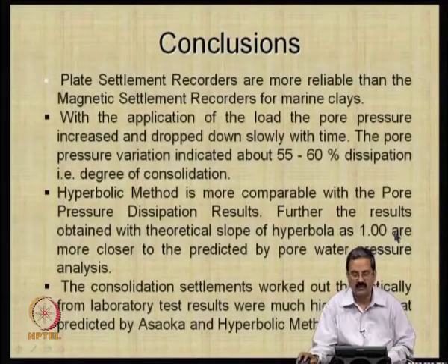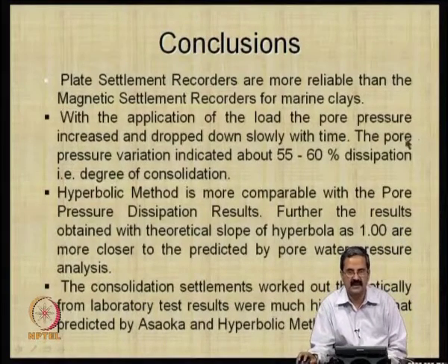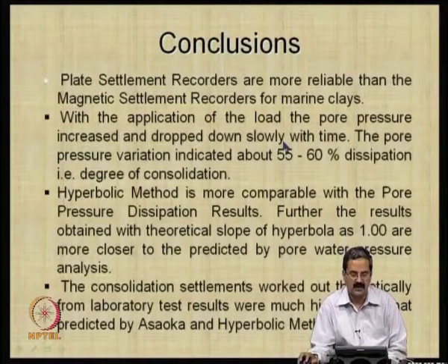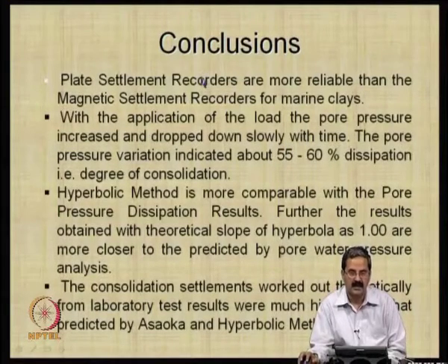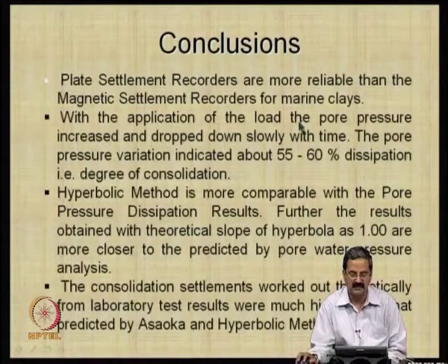What was found was that some of these case studies are only specific to that particular problem, and also depend on the ability to interpret the available data. So, what was observed was that the plate settlement recorders are more reliable than the magnetic settlement recorders for marine clays. With the application of the load, the pore pressure increased and dropped down slowly with time.